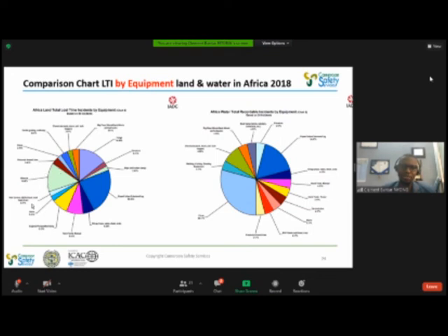We have well-control equipment; during BOP maintenance there's also a high risk of incident because we have to nipple down and nipple up the BOP, and the hands will come in contact with hammers, spools and all those. So they account for a high measure of incidents.